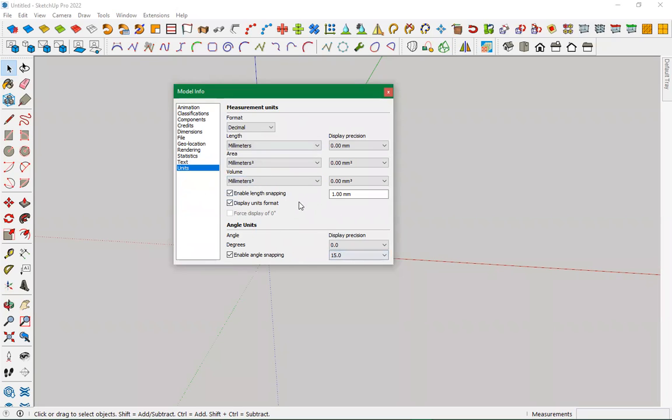If you're using millimeters and you want to input something in feet and inches, you can just do that using this box. So I'm just going to finish up this setup and then close it. So you see how it goes. For degrees, I'm going to use this also. Enable snapping every 5 degrees. I want to leave it at 5. Yeah, so it's pretty close. So I'm going to close this.